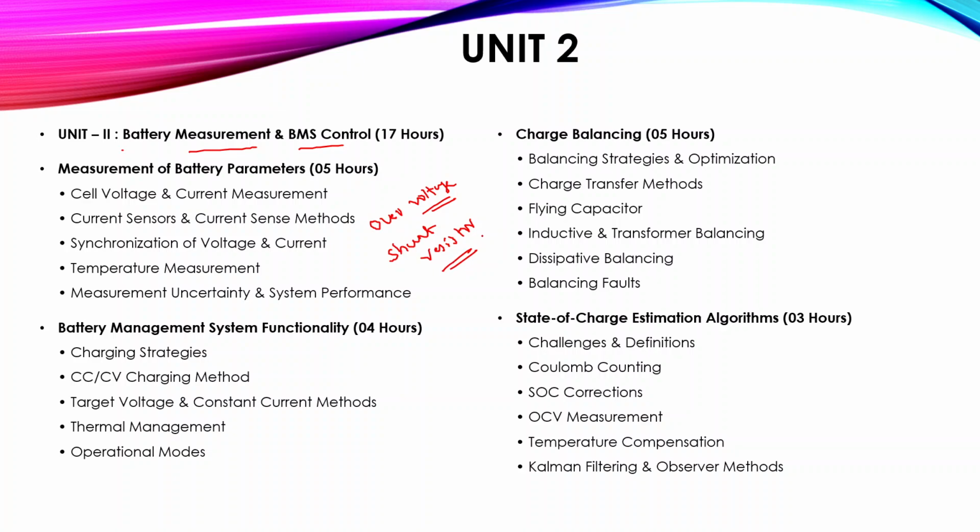Now, synchronization of these current and voltage measurements is important for accurate SOC estimation. This temperature measurement is equally critical because battery performance and safety are highly temperature dependent.